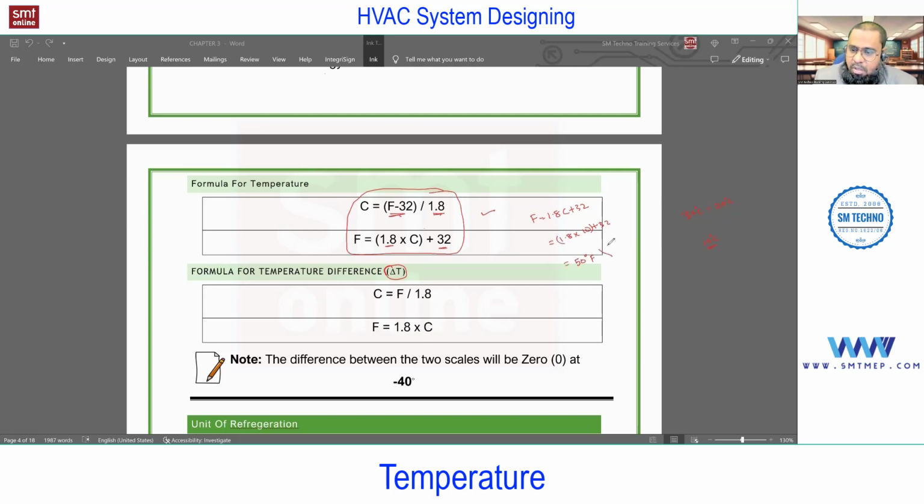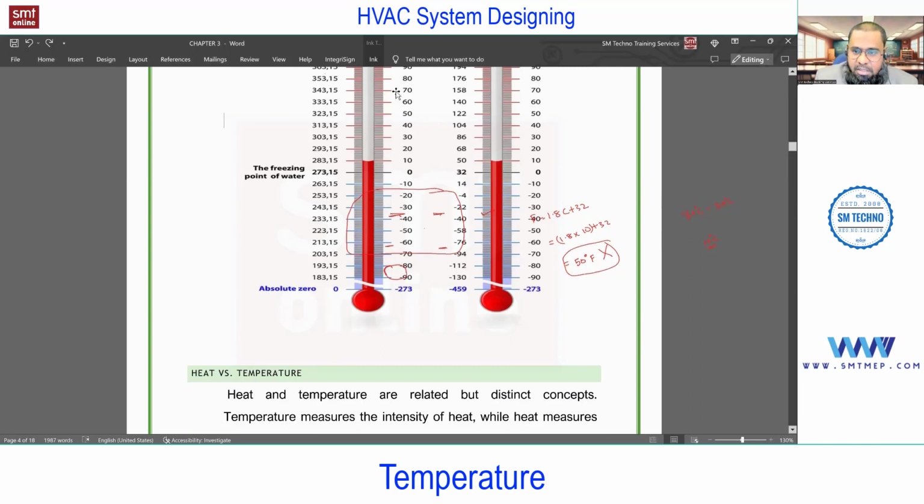So this is going to be a big mistake. Here, 10 degrees centigrade in terms of Fahrenheit is 50. There is no confusion in this. But why am I saying this is wrong? Because this 10 degrees centigrade is not a temperature on the scale. This is a difference of these two temperatures. So in that case, the starting point is not applicable.